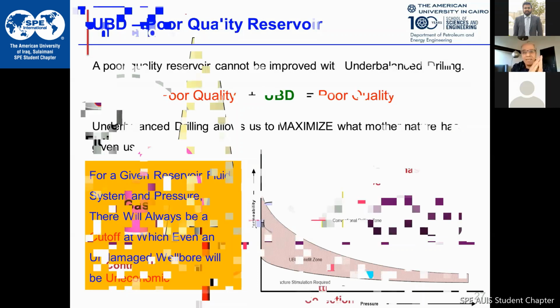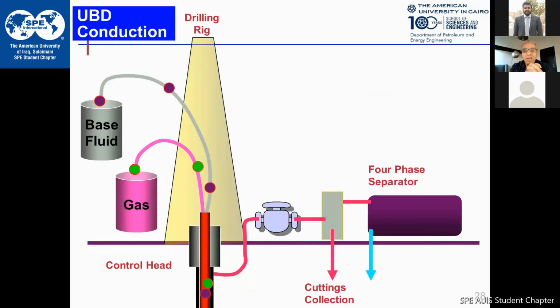So how is the technique conducted? In terms of the drilling, I mentioned earlier that the mud, let's say water-based mud in here, has a density of 1,000 kilograms per cubic meter. Now we can add some material to the mud, bentonite for example, so the density gets larger. To reduce the density in order to reduce the value of hydrostatic pressure, we inject gas. We inject, for example, nitrogen, which is quite safe.